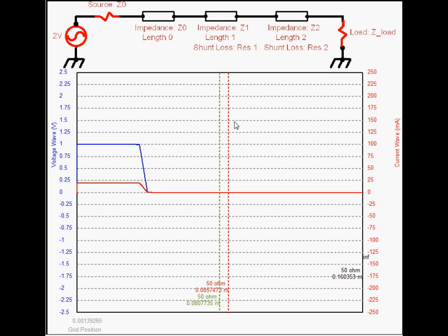So here we're going to show what happens when we have the open case. Again, it's the exact same at the start until about 10 nanoseconds later at the source side. You don't really know what's happened at the termination. It all looks the same. But here, going into an open, we have a positive voltage wave that comes down and sums to 2 volts, and a negative current wave. That negative current wave sums with the incoming wave and makes it 0.